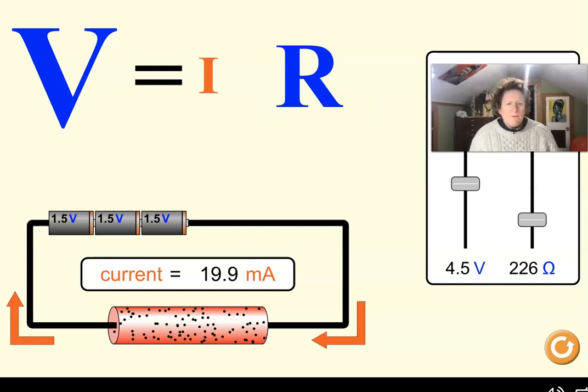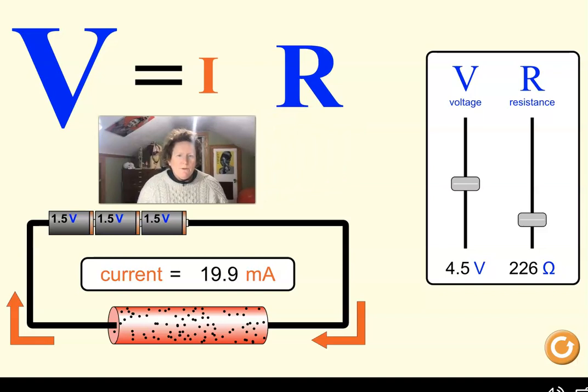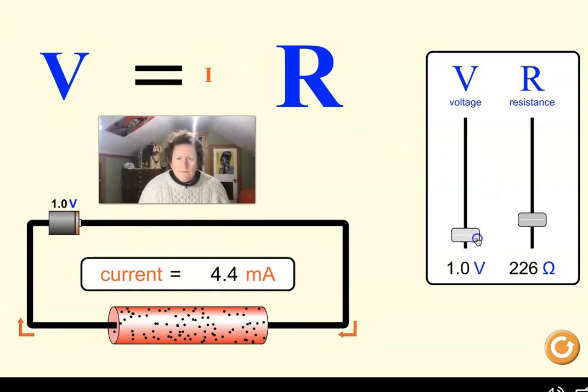We're basically going to experiment with different levels of voltage, current, and resistance. We can change the voltage and resistance here, and we're going to look at how that changes current. Current is the I here in the equation. This equation says voltage equals current times resistance. The current you can read here, and the relative size of the current will be shown by I. If the current gets smaller, the I will get smaller, and this number will also get smaller in milliamps.